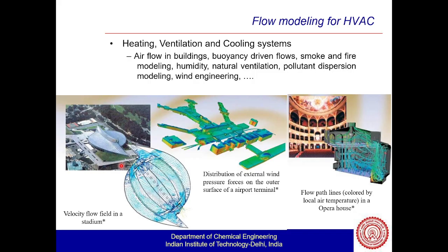And basically, you can see the buoyancy driven flow. You can also simulate fire, smoke, natural ventilation, and pollution dispersion models using CFD. So, how pollutants get dispersed from a primary source and how it changes over the whole domain. For example, if there is a chimney in the city and you want to see how the pollution concentration changes with distance, on a spatial and temporal basis, you can do it.